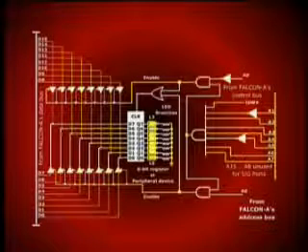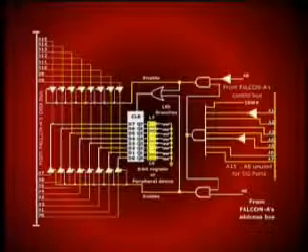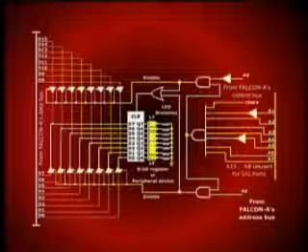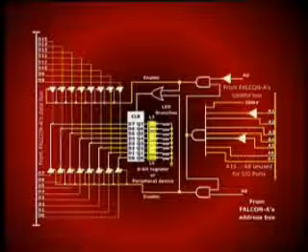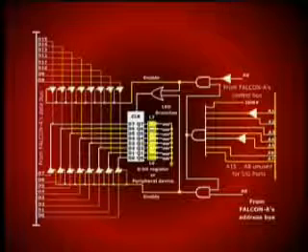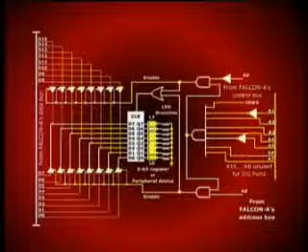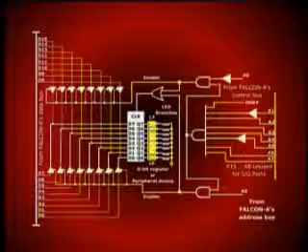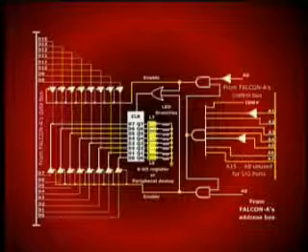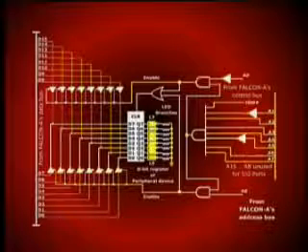For an even address, A0 is equal to 0 and the upper group of the tri-state buffers is enabled, thereby connecting the data from the bus with bit 8 up to 15 of the CPU to the peripheral, while for an odd address from the CPU, when A0 is equal to 1, the lower group of tri-state buffers would be enabled.